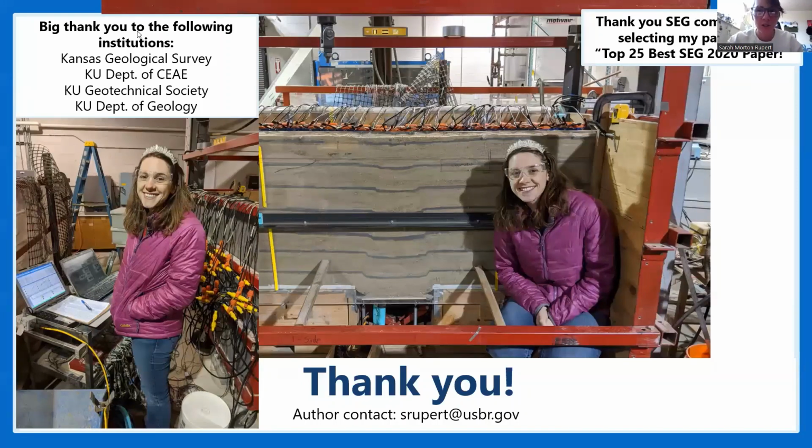some of the changes we did from test to test, you can kind of see here in this picture. You can see how there's actually a gap in the sand. So what we did was we used a geotextile that we laid across the trapdoor, and we used that to simulate the bowing effect that happens, because obviously the roof isn't just going to have a block slowly move downwards. So we used that textile to simulate the bowing effect. Hopefully that answers your question.